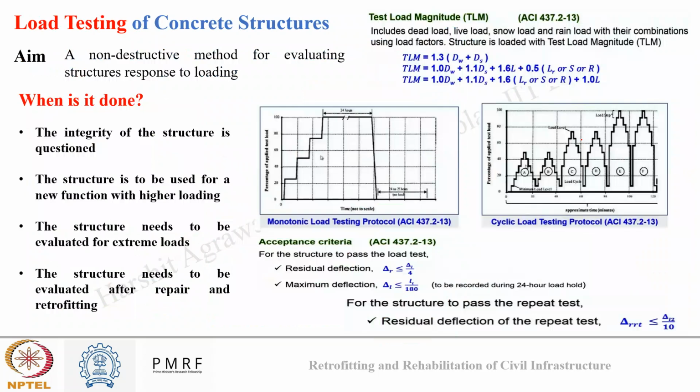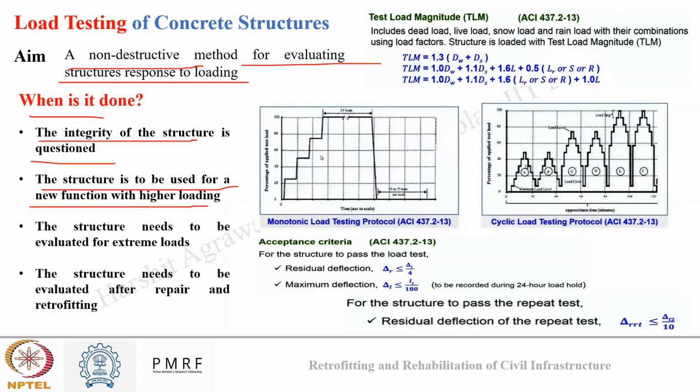After this, there is one more important and often practiced on-site testing, which is known as load testing of concrete structure. So, the aim of this testing is to non-destructively evaluate the structure's response to loading. Now, it is done when we need to check the integrity of the structure, when the integrity of the structure is questioned. And secondly, when the structure is to be used for a newer function with higher loading, then we need to conduct a load test to check whether the structure is safe or not.